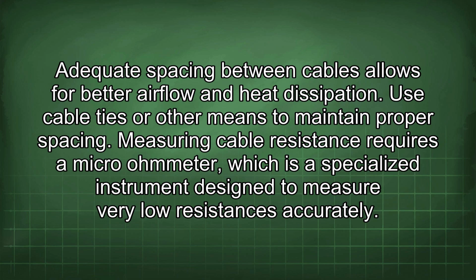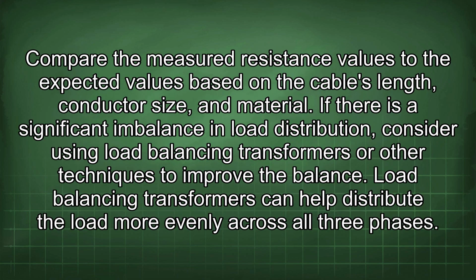Measuring cable resistance requires a microohmmeter, which is a specialized instrument designed to measure very low resistances accurately. Compare the measured resistance values to the expected values based on the cable's length, conductor size, and material.